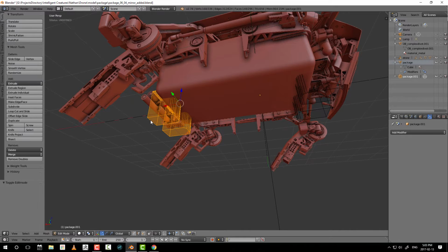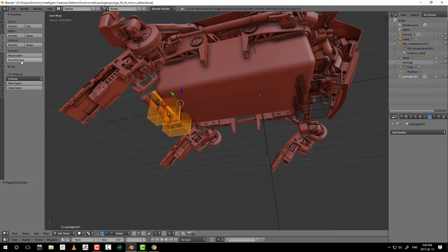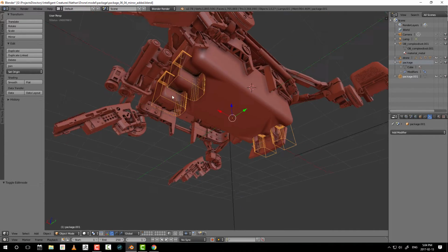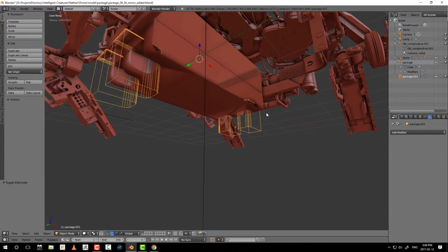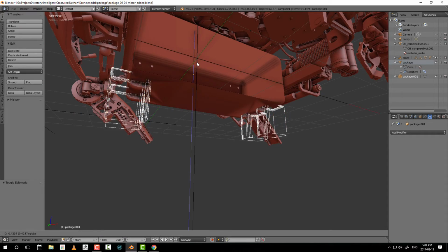So I'm going to enter the object again, and now under shading and UVs, I'm going to go and flip the direction of the normals, right? So here it says normals, flip direction. And now when I tab out, you'll notice that it works. And again, if I move this up and down, it works all the way throughout for every part of the object.